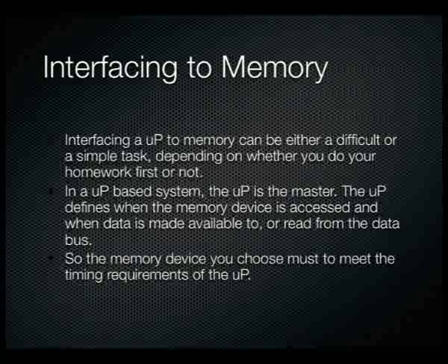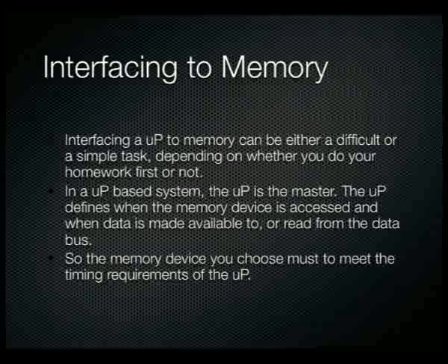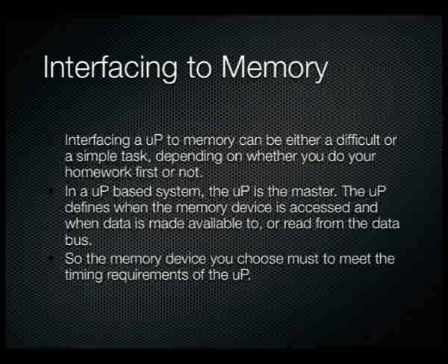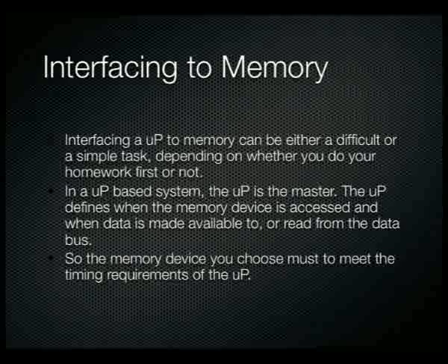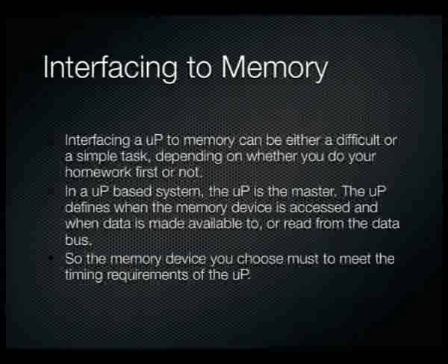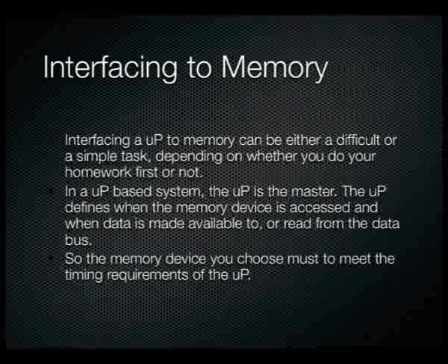So as I said before, generally during a read transaction, you simply put the address on the address bus, you set the read line in the control bus, and then you wait a set number of clock cycles, and then the microprocessor will sample the data bus.